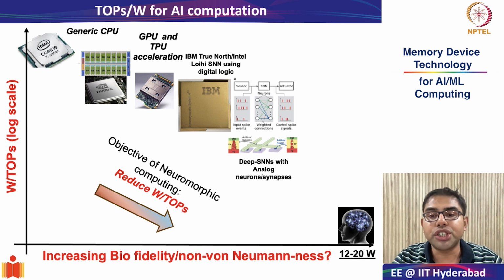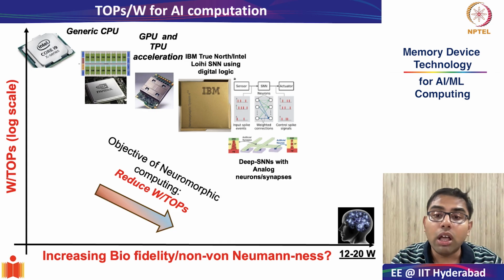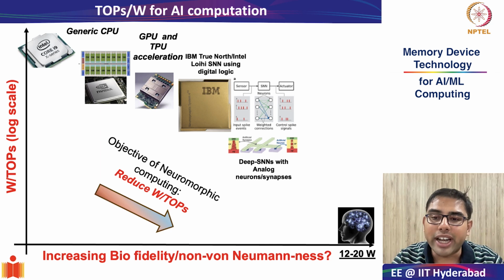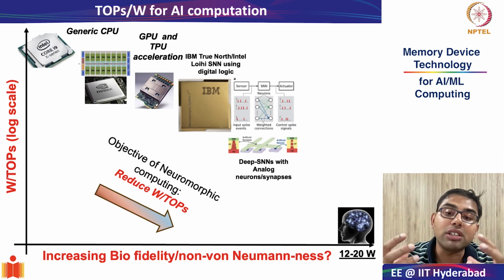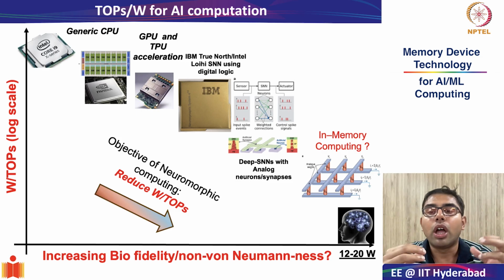So this naturally led us to the idea of using mixed signal spiking neural network implementations, such as we saw in BrainScaleS and also in Neurogrid chips. These platforms use analog neuron and synapse dynamics for energy efficient computation, but surround them with digital control and communication networks for better scalability. And this hybrid approach, or the mixed signal approach, combines the best of both worlds, the analog efficiency and the digital stability and scalability.